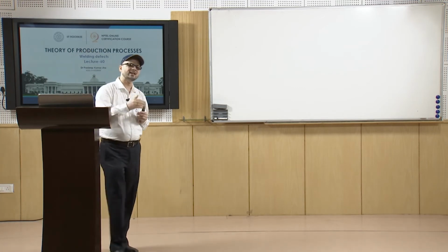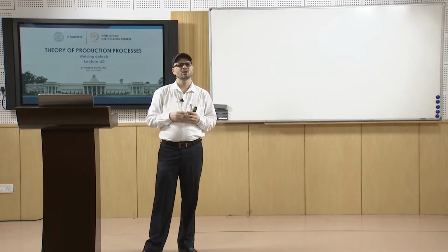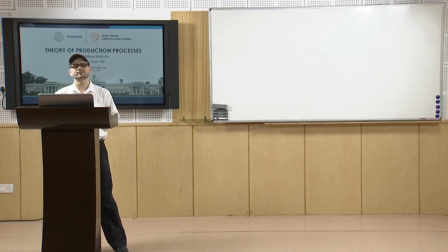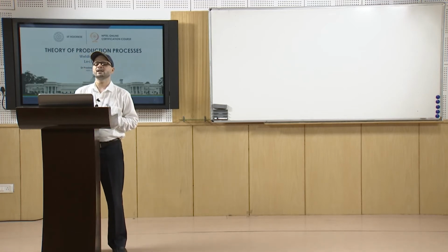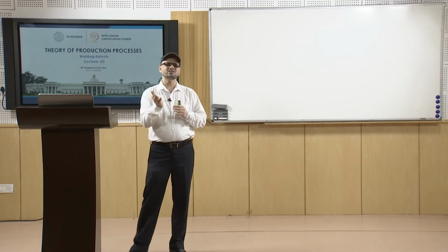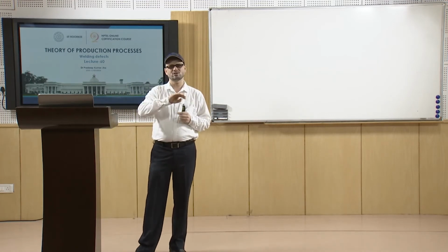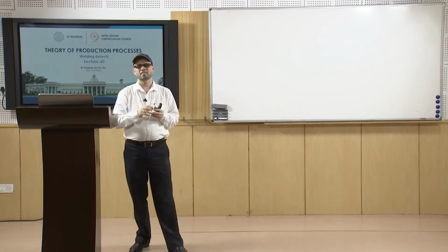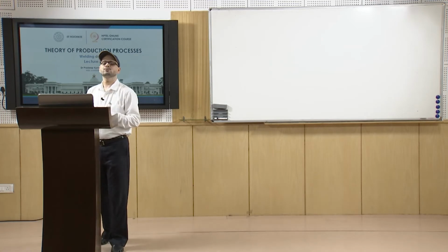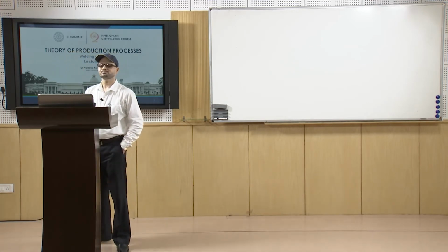You also have the cases of excessive penetration. Excessive penetration also comes under this category of imperfect shape type of defect. Then you have weld bead shape. That shape may have a convex type of structure or a different improper shape of the weld bead, which is also a defect and comes under this category of imperfect shape.